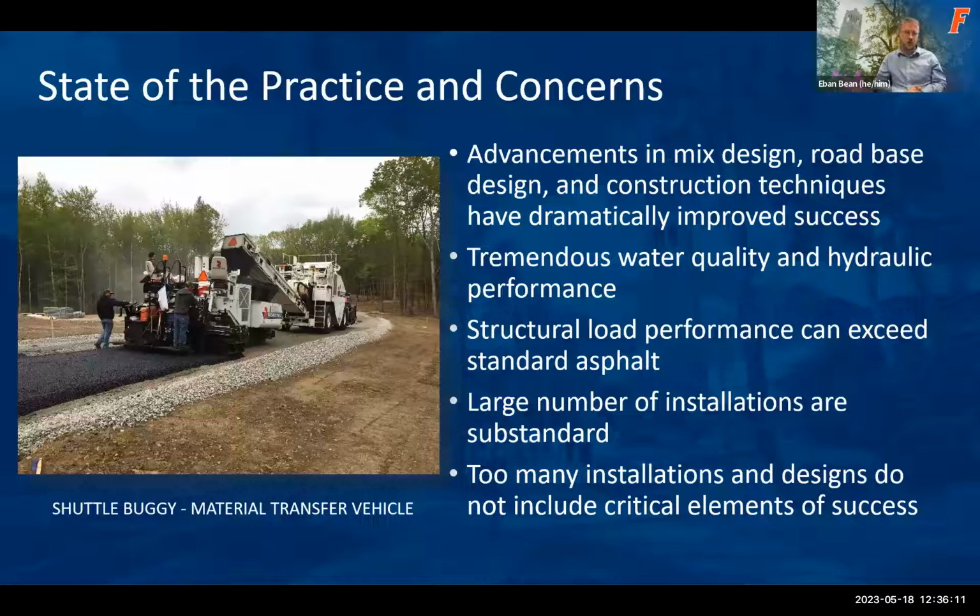The structural load can actually be stronger than standard asphalt, because of that sub base, a mixture of the choking layer and asphalt, which has a thicker profile. There were a large number of installations that were just poor and the mixes were not well done. I think that gave porous asphalt a pretty bad name, but that technology has really matured in the past 10 to 15 years.